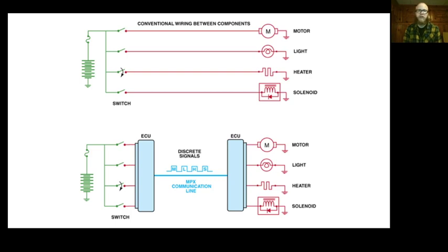You can't say, oh, my PCM went bad, I'm going to take my body control module, plug the connectors into that one, and then all of a sudden, if I just reprogram it, I can use it to run my engine and my transmission. No. It's limited by the structure, and those are a couple of those parts: the actual circuit board and the read-only memory.